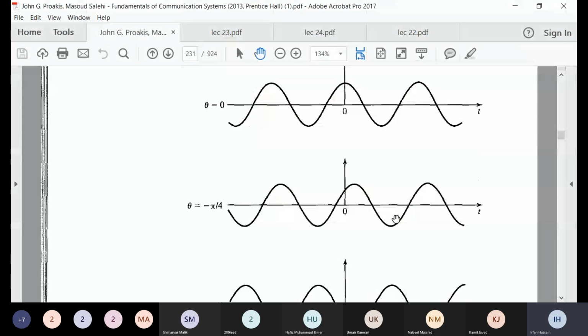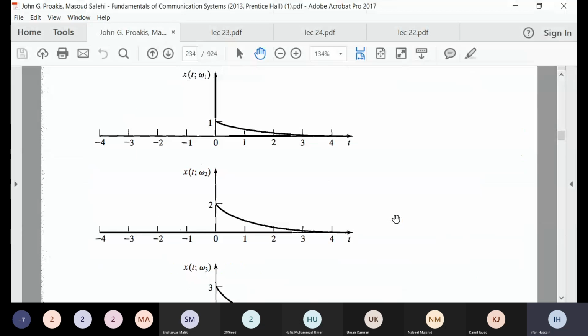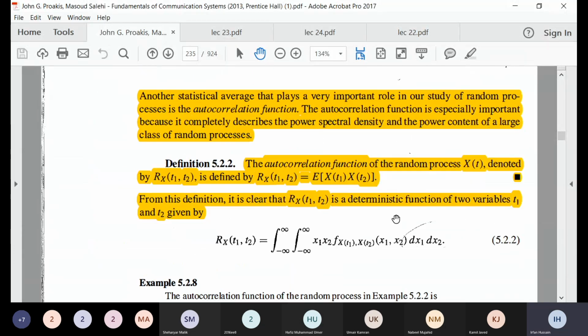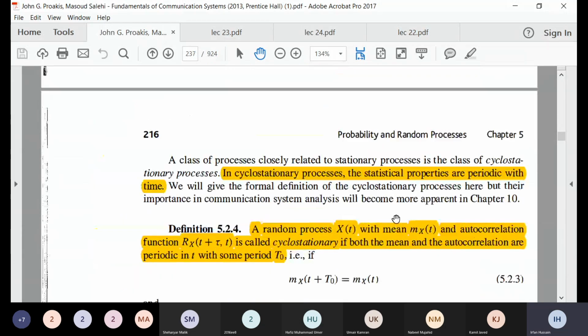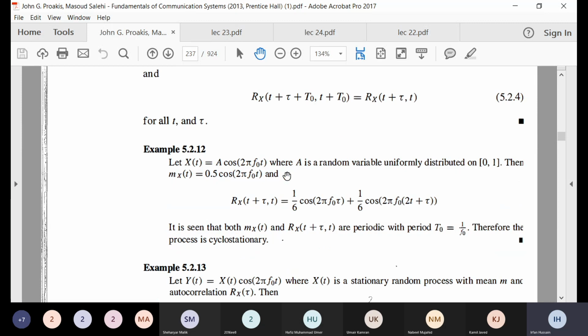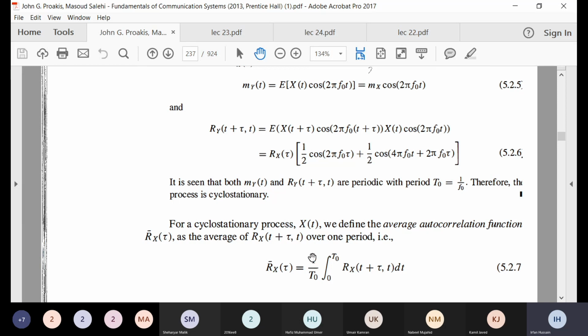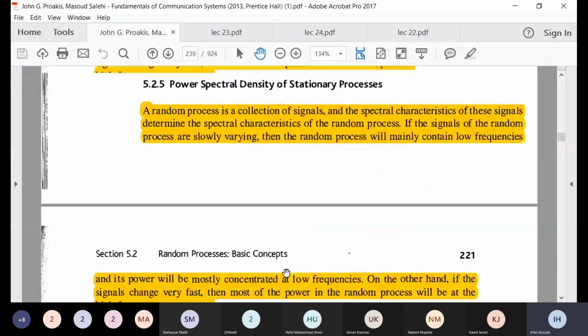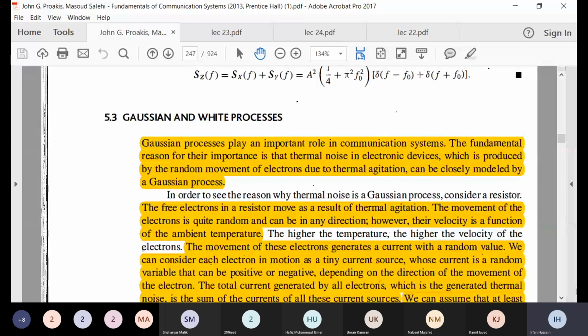And so random processes, this was in the course, but one thing was not. Now here we saw white cyclostationary processes. For cyclostationary processes, which are a function of t and tau at the same time, we take the average with respect to t, and then for the average value we find its Fourier transform, and then we can find its PSD. This is the way we have to proceed with a cyclostationary process.